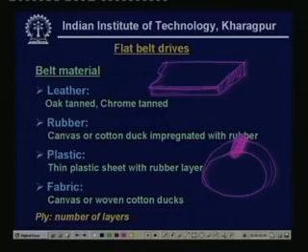So, what people do is they can use a cemented belt from the factory itself, or with care one can join these belts with various clip systems that are available in the market. Normally, flat belt drives do not have any limitation of center distances. It can go as long as possible.